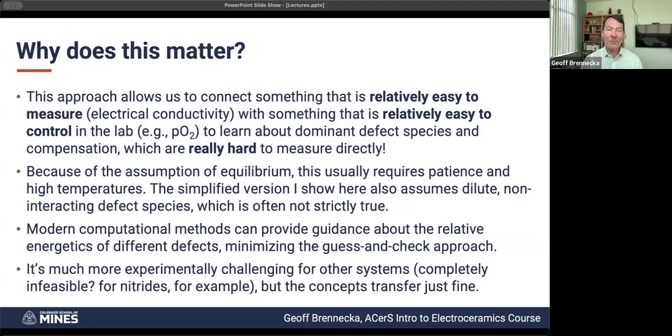But yeah, the examples that I've given you here are intentionally very simple. A nice, easy, single phase material, single crystal structure, nothing complicated. As you start adding more and more complications, chemistries, and different reactions that can happen, then yeah, you're just going to get more and more complex. The important thing to keep in mind, though, is that no matter how complex the system is, you are still going to be dominated by whatever the most likely defects and defect compensation mechanisms are.